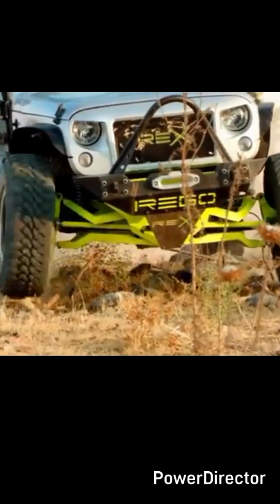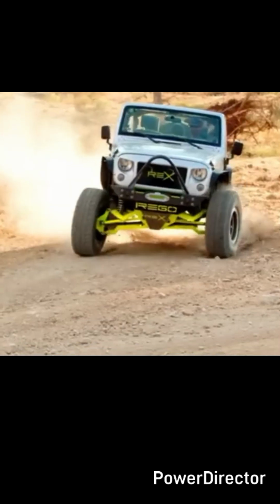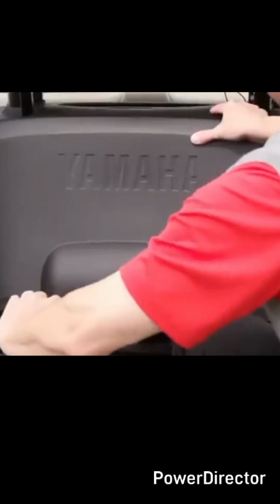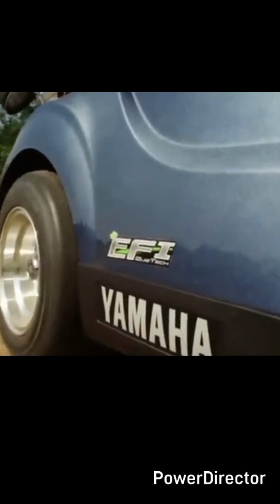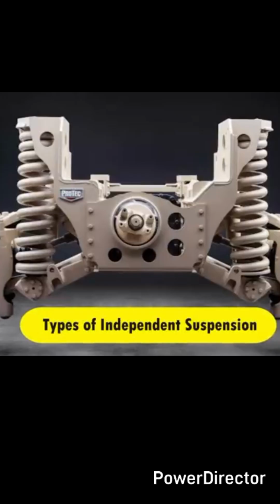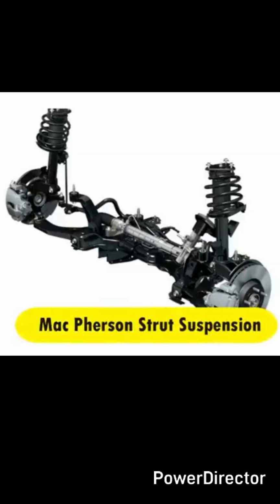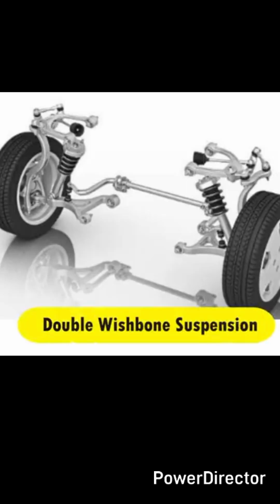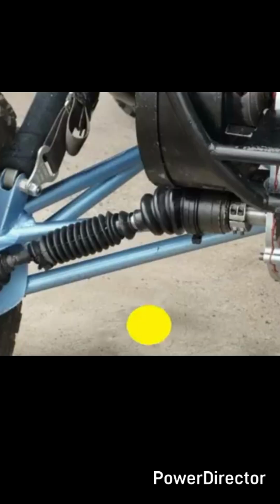It is common for the left and right sides of the suspension to be connected with anti-roll bars or other mechanisms. Most modern vehicles have independent front suspension. Many vehicles also have an independent rear suspension. It has almost the same advantages as the independent front suspension, but the main advantage is that it reduces the unsprung weight of the vehicle. In independent suspension, there are various types available. They are MacPherson strut suspension, double wishbone suspension, multi-link suspension, and trailing arm suspension.